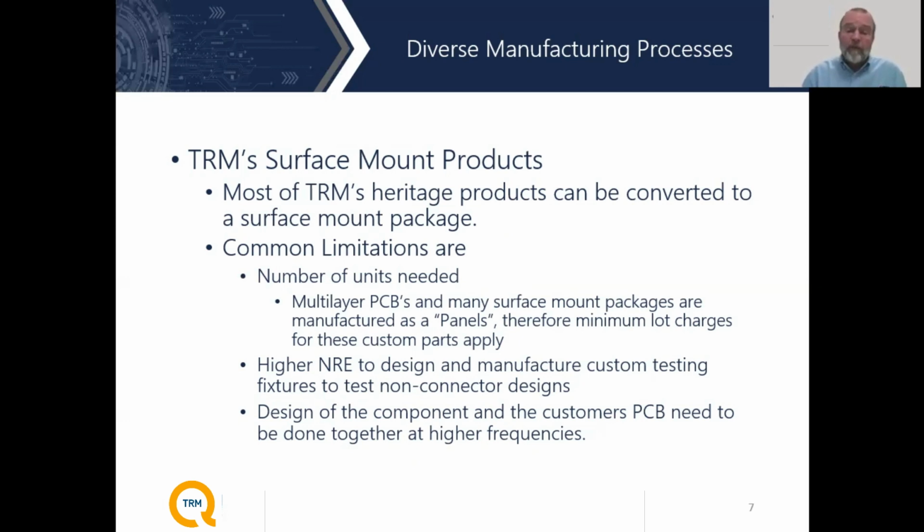What I will say from a limitation standpoint is that from a cost standpoint, when we build these multi-layer PCBs for these surface mount components, we get the yield of a panel whether we like it or not. So if you want to get 2 or 3 of them, which is a very low number, kind of typical for a lot of our customers, the cost per unit is still substantial because we have to pay for the entire panel.